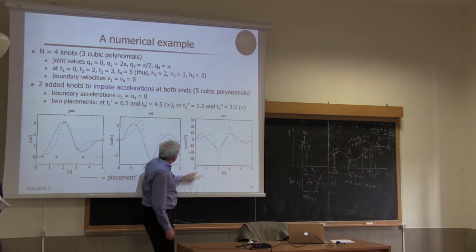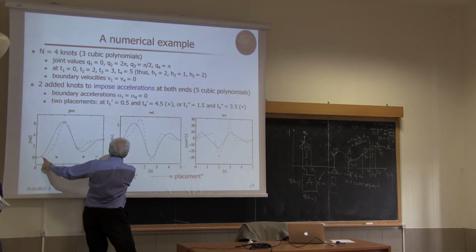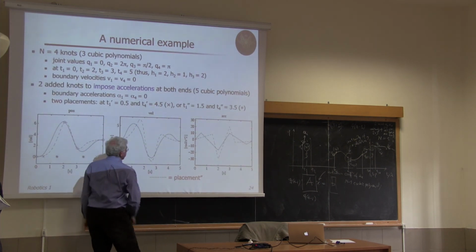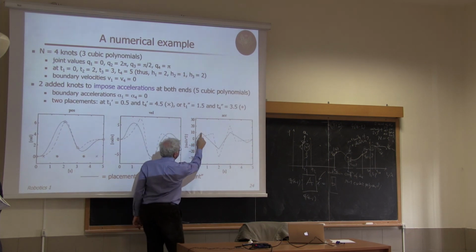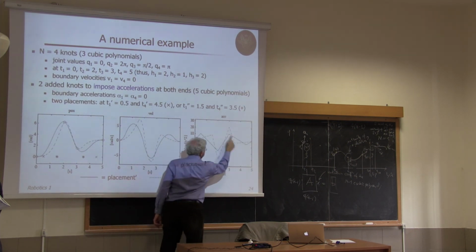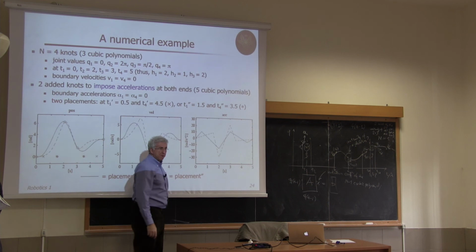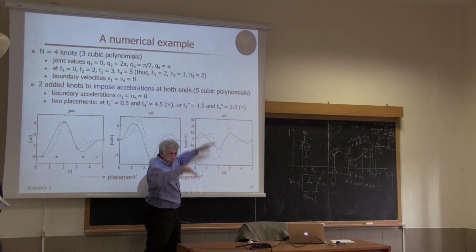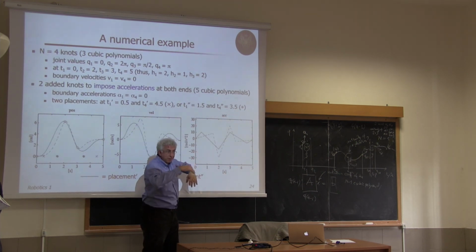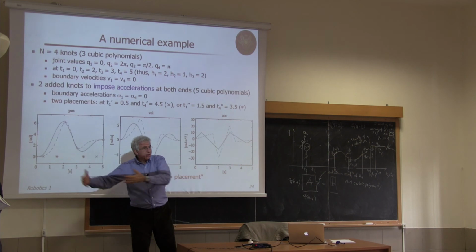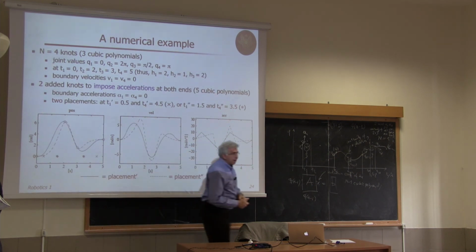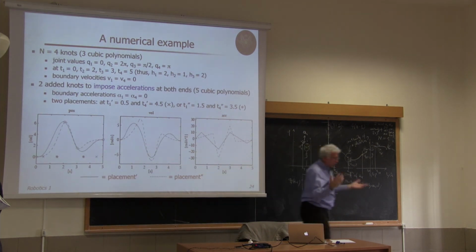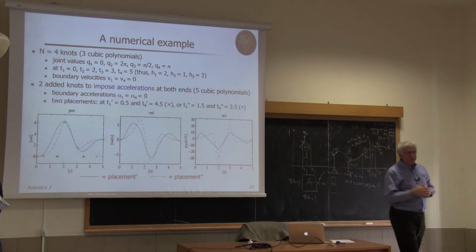And you see when you're splitting with x's, so with the short initial and final interval, this is the first segment, second segment, third, fourth, fifth segment. Okay? So it's linear in acceleration and continuous, although the jerk would be discontinuous in this case. In fact, this would require higher order cubics, higher order splines, not cubic spline.